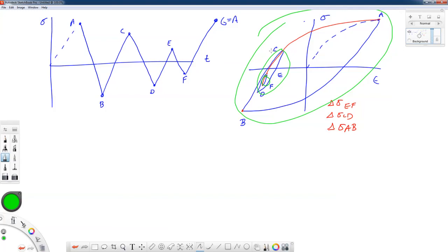It all can be operated on with just our one variable, our active time history of stress, sigma, or whatever active history you have. So rainflow cycle counting can be done on stress, strain, time, temperature, whatever. We're only looking at the change in the ups and downs of that one variable with respect to time, but we have this equivalence to finding these closed hysteresis loops on our stress strain plot.